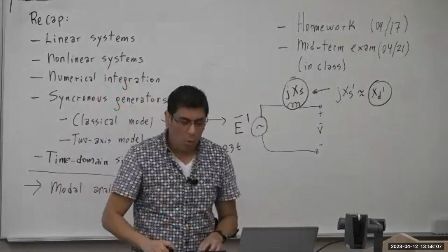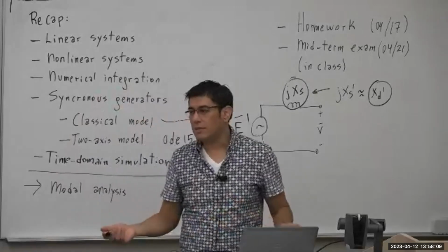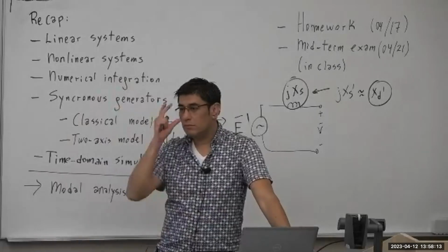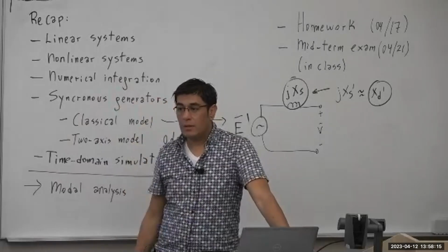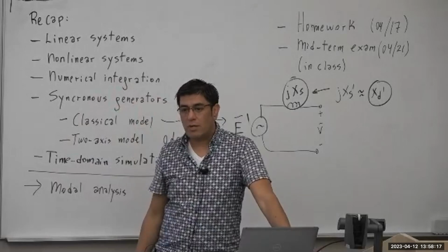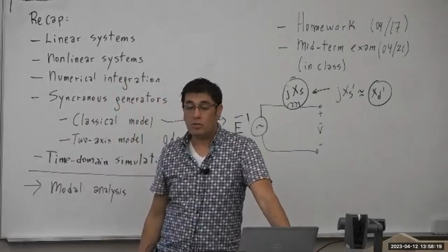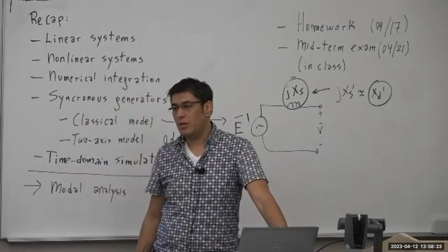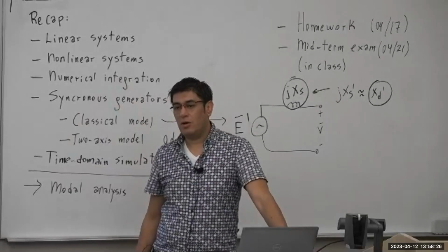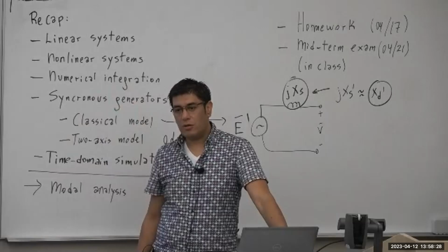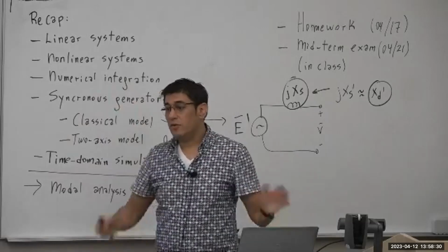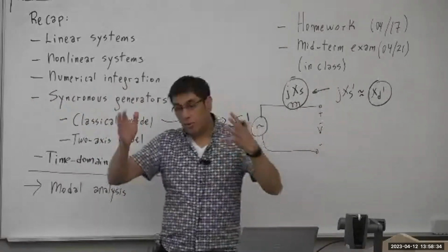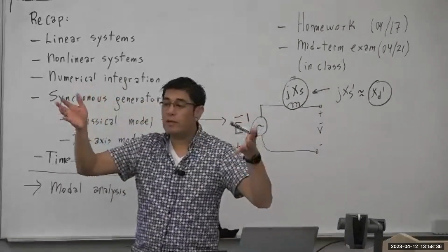And what is the impact of more energy oscillating with the infinite bus? It's like a train. Can you stop the train right away? No. Probably it will slow down. What about the frequency? What happened with the frequency of the oscillation? Probably the frequency would go down, right? Yeah, so the period of the oscillation would increase in that case, but potentially, because not always that mode will